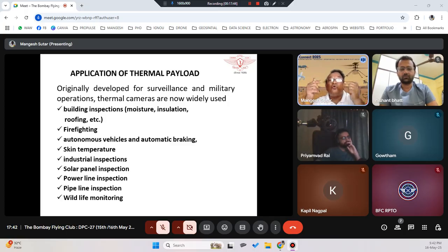Okay. So if you know that wire is getting enormously heated, maybe that particular junction of that wire may be faulty, or you may have to get it replaced, or it may break some other time. So instead of waiting for the disaster to happen, we should always take proactive measures. So if we know that it is going to break and it is in a worse condition, we can take a decision, take a downtime and replace that wire.